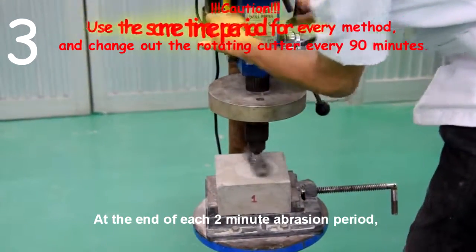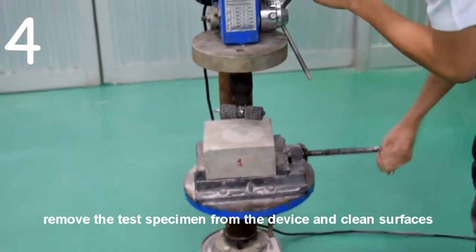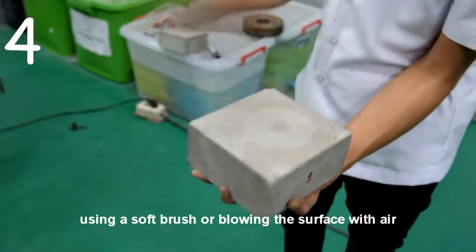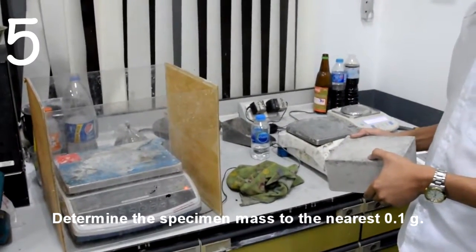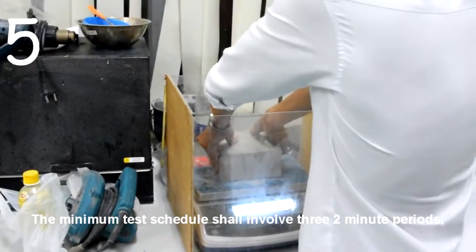At the end of each 2 minutes abrasion period, remove the test specimen from the device and clean the surface to remove the debris using a soft brush or blow the surface with the air. Determine the specimen mass to the nearest 0.1 gram. The minimum test schedule shall involve 3 2-minute periods.